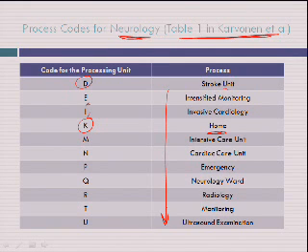What they did was, even though they began with these departments in the new hospital, they split these departments, they combined certain departments. And this is what is fundamentally different from the way we keep building hospitals in the US. We just take the same departments and put them back in the new hospital. These people decentralized and combined and made hybrid departments. And that's basically what production flow analysis in all 4 stages helps you to do. And the benefit is that you get the 7 types of waste whacked out because you're going towards cellular systems of manufacturing.